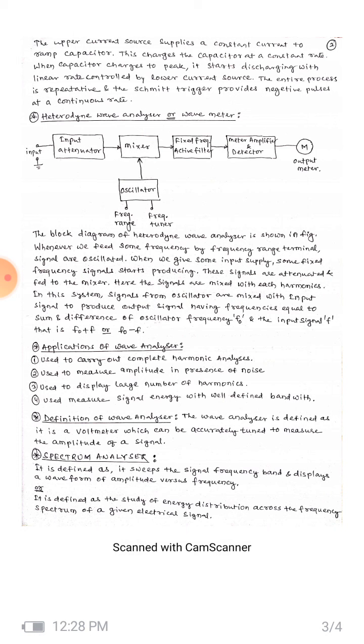The input signal to be analyzed is heterodyned to a higher intermediate frequency by an internal local oscillator. Tuning the local oscillator shifts various signal frequency components into the passband of the IF amplifier. Then the output of the IF amplifier is rectified and applied to the metering circuit. The operating frequency range of this instrument is from 10 kilohertz to 18 megahertz. The bandwidth is controlled by an active filter and can be selected at